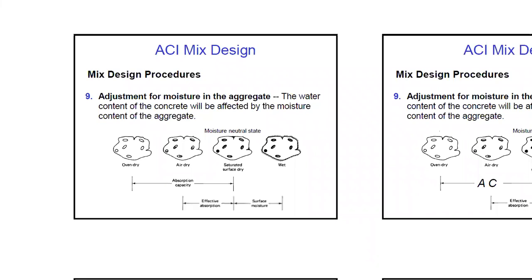Basically, we need the moisture to be there so that the concrete gets lubricated, the aggregates get lubricated, and they start workability, like they start flowing. So the surface must be wet enough for the concrete to start working, you see. So for that reason, you need to have the concrete wet, the aggregates in wet condition. Now, there are four conditions that are discussed over here.